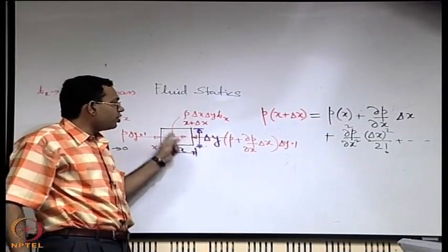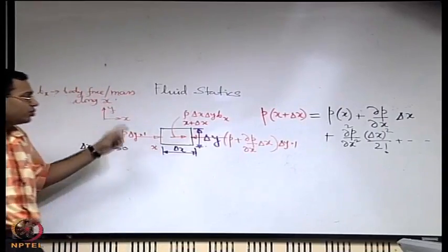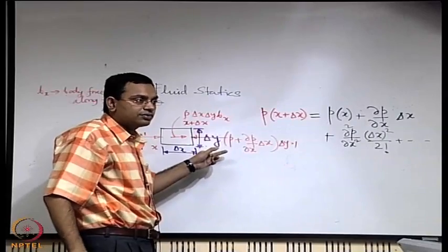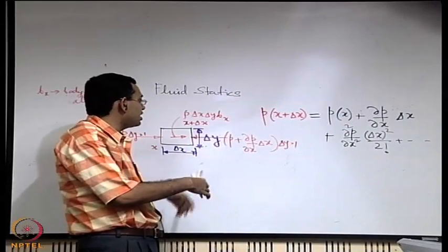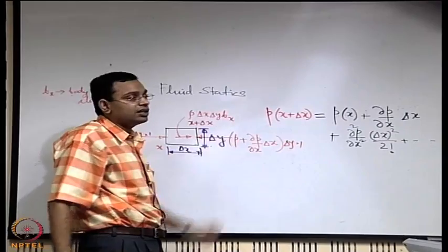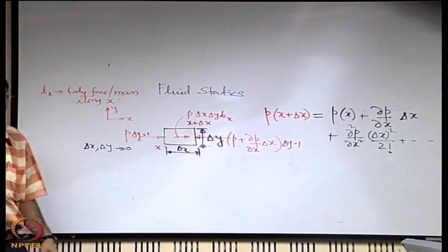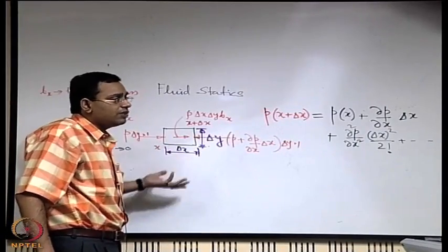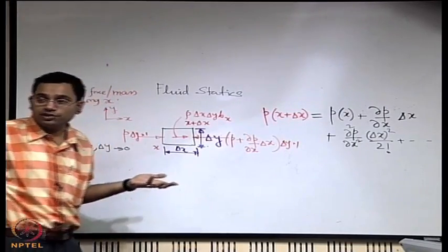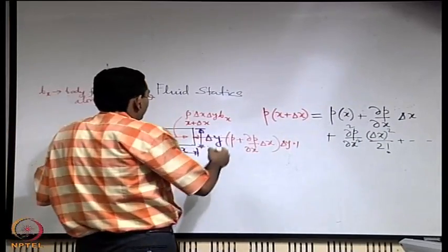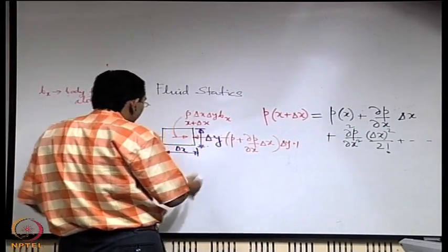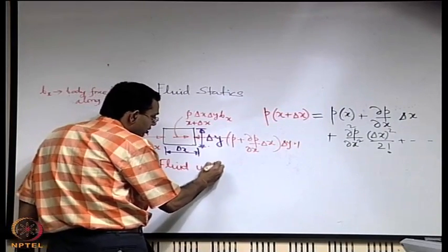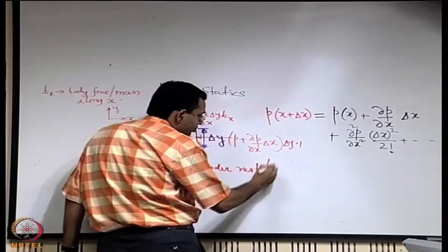So, for a non-deforming fluid element, there is no difference between the surface forces which are presented in this diagram and the surface forces which are there when it is moving with an acceleration. So, this type of forcing description is equally valid if the fluid is under rigid body motion. So, we identify this situation not just as fluid at rest, but also rigid body motion.